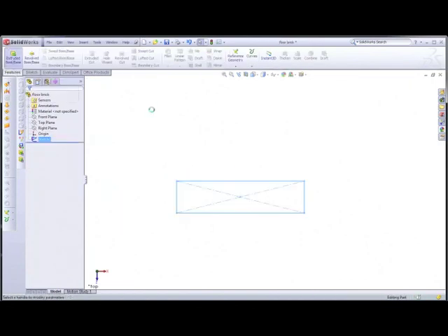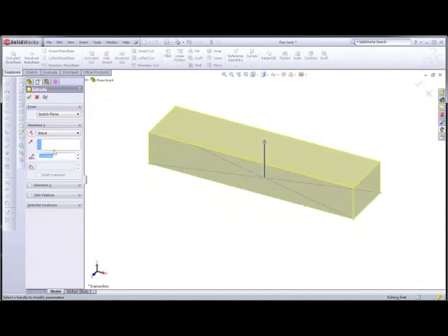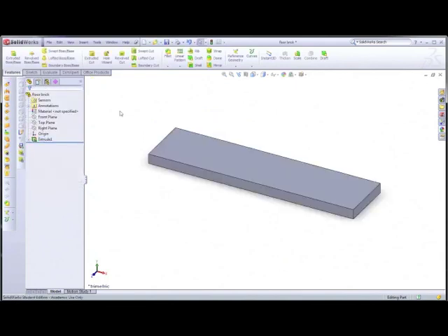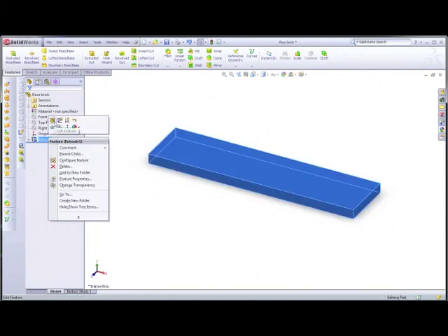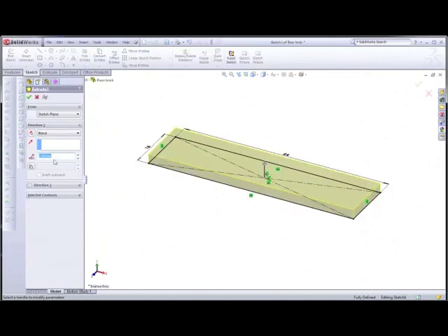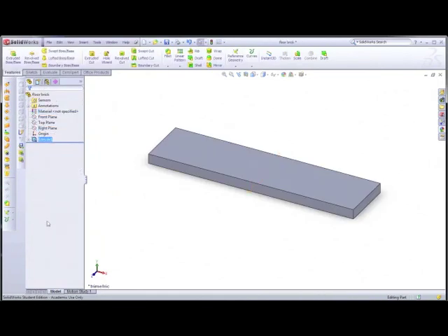Click extrude. Now we want to extrude this only 3mm. So type 3 in the box down here for dimension and green tick. Okay, guys, remember, if we get anything wrong in there, say if you put 4 and it's actually 3, what you can do is go across, right click again, go edit feature, and you can basically change anything that you've done. And this goes for if you've got a massive long history tree, you can always go back and edit something, so it's not difficult. And the same goes for the sketch, but I'm not going to show you how to do that for now.